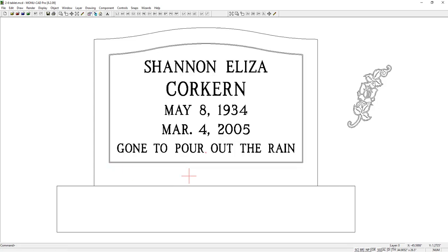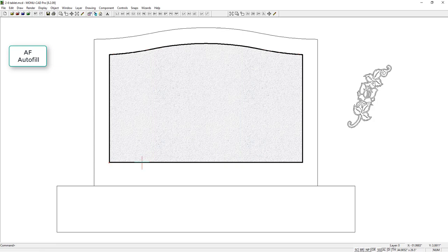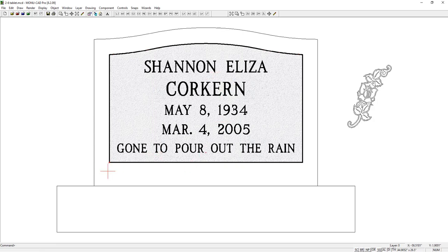Instead, what we do is use an autofill, AF. We choose anywhere along the outside of this box, and I'm going to choose right here, and it fills our box and our V-line.